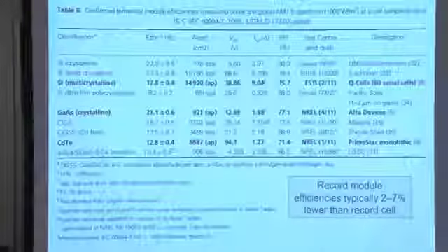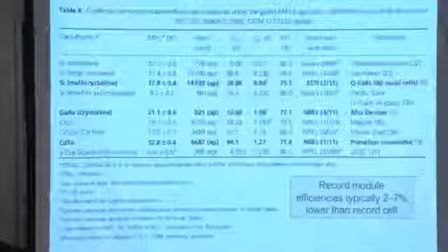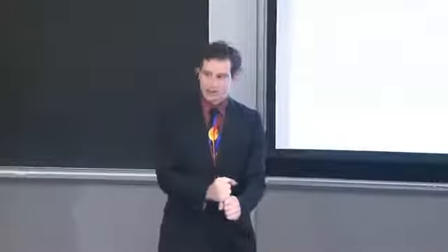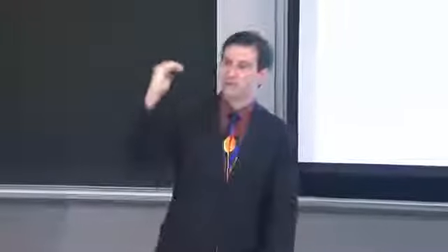One analogy, since I know many of you are mechanical engineers, is when you're doing tensile tests with ceramics or brittle specimens at room temperature. You pull on your specimen and you obtain a certain fracture stress. You then take that smaller piece, pull again, now the fracture stress is higher, pull on that smaller piece that broke off yet again, and now the fracture stress is even higher. In other words, in that large specimen, there was one point that was extremely weak, another point that was sort of weak, and another point that was mildly weak, right? And as you increase the size of your specimen, the likelihood of having one of these failure points increases.